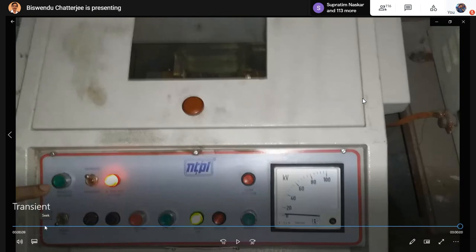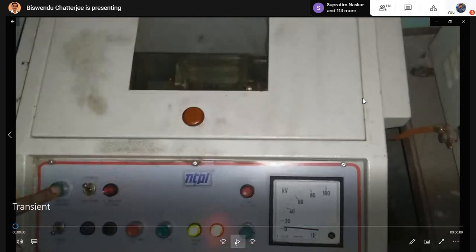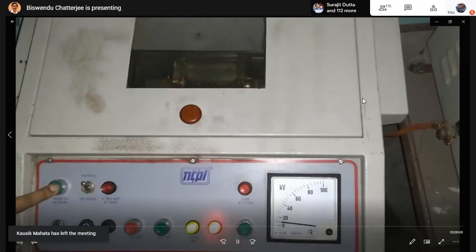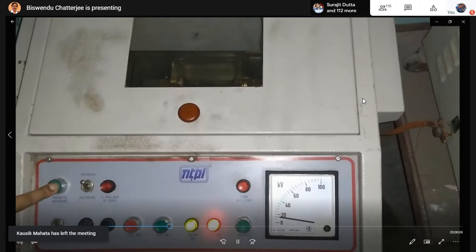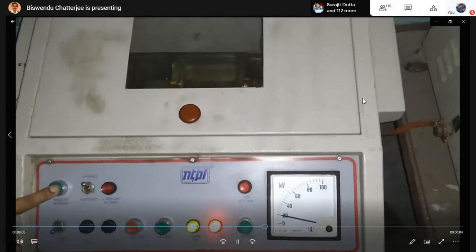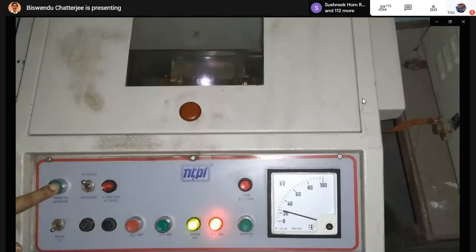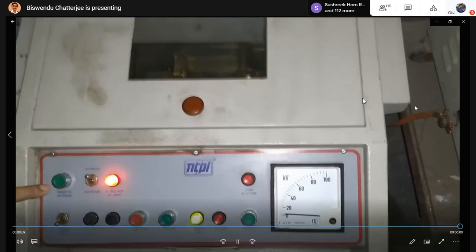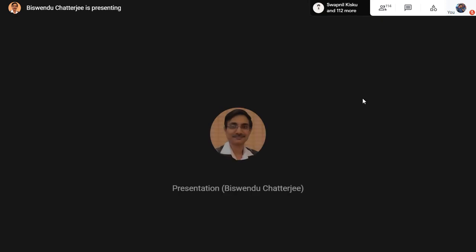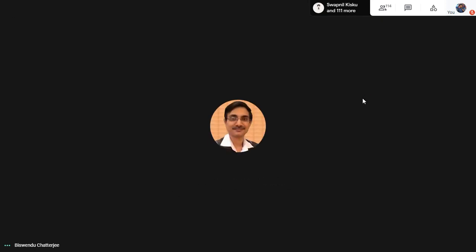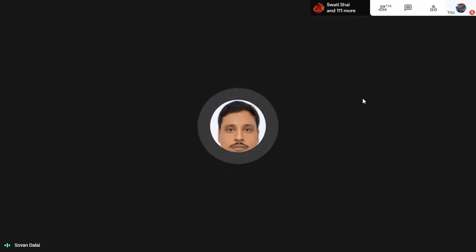Now start from the beginning and see clearly. Now a transient occurred, nothing happened. Now it will be the final breakdown. Yes, these are the two things. I think it is now clear. And the basic logic behind it is that transient breakdown occurs due to impurities attached to one of the electrodes, which reduce the gap.